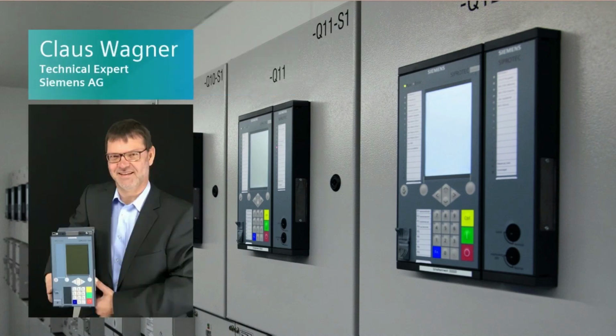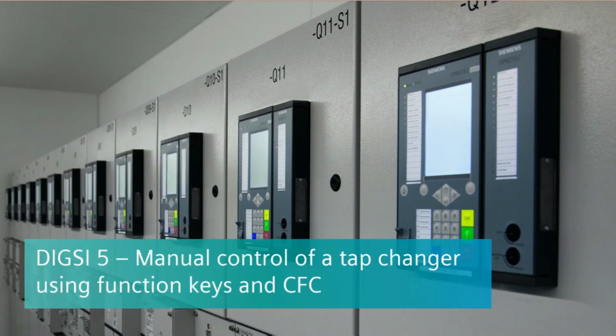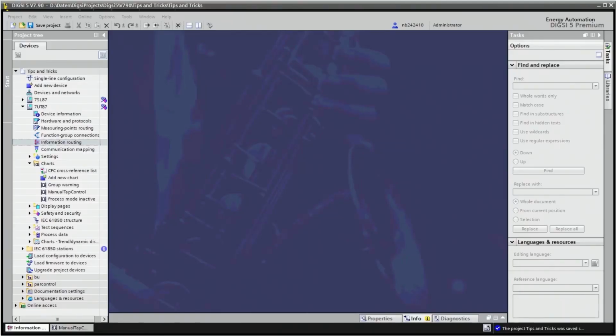My name is Klaus Wagner, and in this video I would like to show you how to program the manual control of the tap changer. To control a primary tap changer with SIPROTEC 5, a function group voltage control is required, which we see, for example, when we open the information routing matrix.